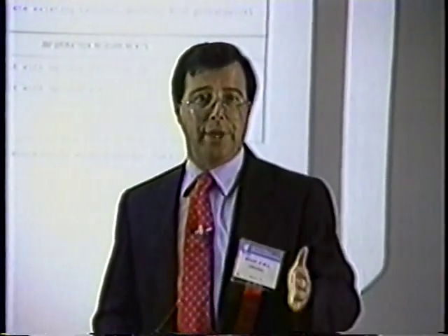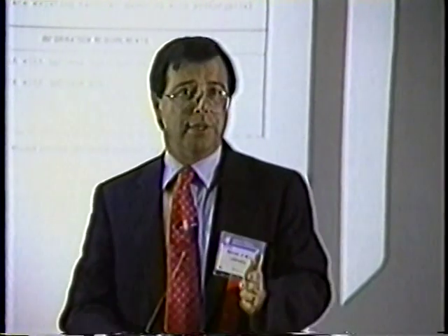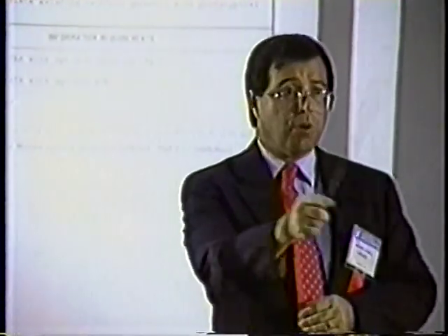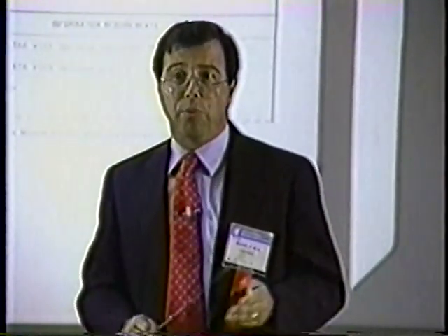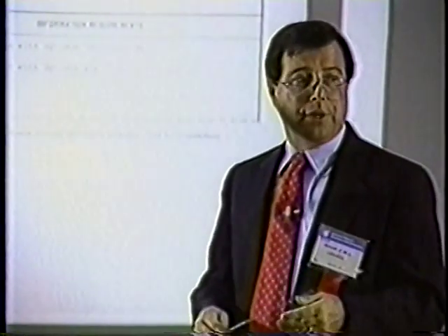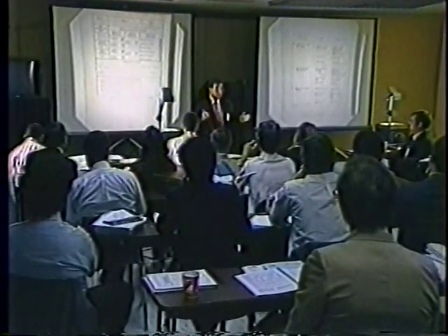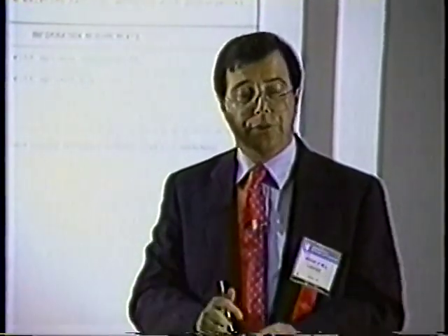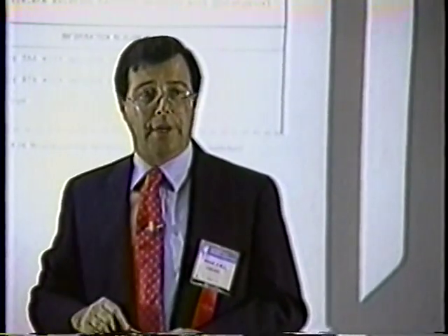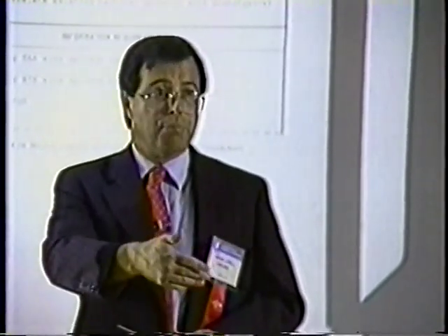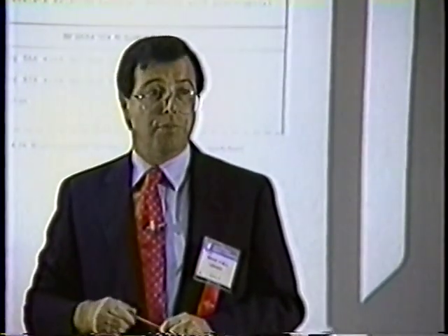We need to correlate what is referred to in fighter weapons school as antenna train angle. That sounds like we've committed to a technology, doesn't it? Antenna train angle. That would be radar. Well, in fact, that's really just the statement within the training curriculum that's the difference between what your velocity vector is and what your instantaneous line of sight to the target is. It does have a radar component to it, but we're trying to keep this separate from the technology that could be brought to bear. Lastly, we do need to know what the range of the aircraft are during the situation itself. This is, of course, one of the fundamental physical parameters and is used to gauge any number of things within it. We tried to keep the number of information points to a minimum so that we can express it simply in a model, analyze it simply in a model, and build the added complexity after we've decided that it's really worth doing.